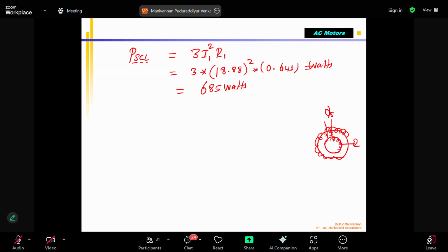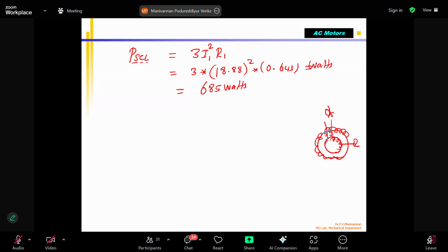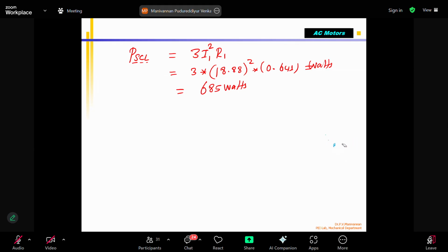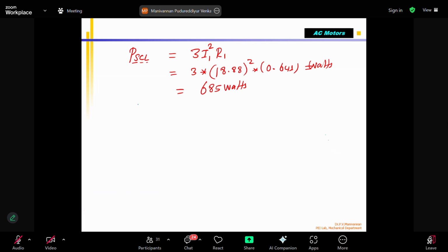So this is the air gap. Because the air gap is circular, annular, the magnetic flux from the stator coil, phi s, goes through it to the rotor and induces a voltage. Then the rotor creates a magnetic flux, phi r, that reacts with this and a torque is produced. Already we know that. So how much power is transferred through the air gap, that is called PAG, power transferred to the air gap. We need to compute it.